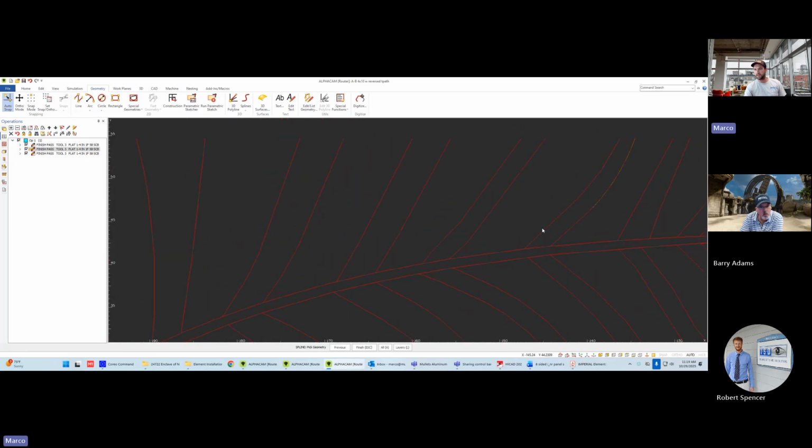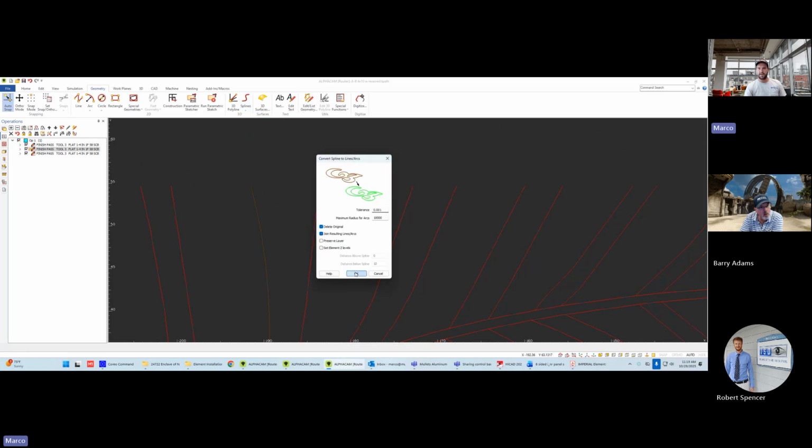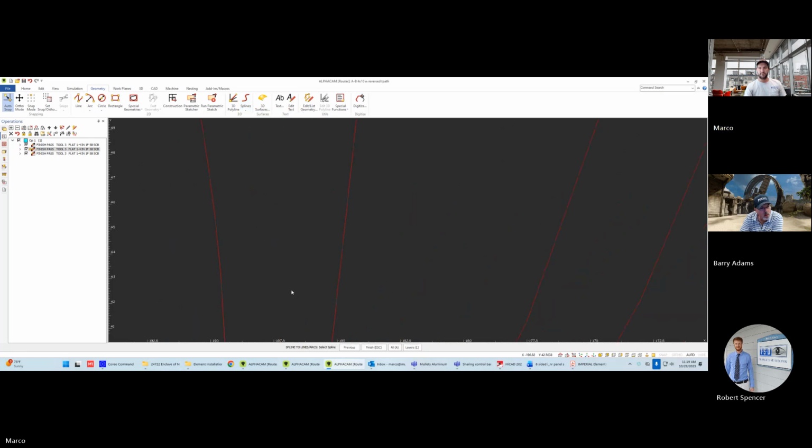I'd break them up into different chunks and stuff. That one changed. Now it's a nice fluid curve, but it doesn't like splines, so then I have to convert that spline back to a geometry. Bam! Nice smooth line. That's one way to do it. I was able to do the whole thing in one shot with P-Edit. Yeah. This one worked out pretty good.